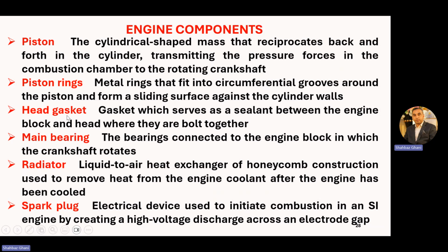Head gasket. Gasket which serves as a sealant between the engine block and the head where they are bolted together. Remember one thing. Whenever you have to bolt or fasten two metal portions, you definitely have to use some gasket material, okay? The material which covers the tolerances.